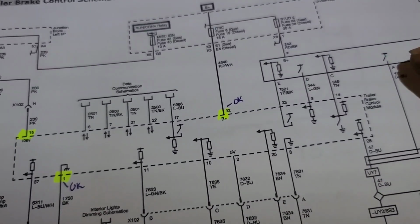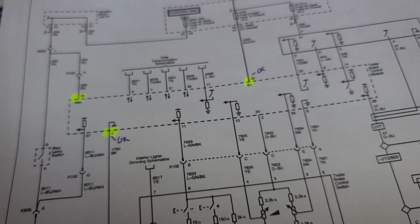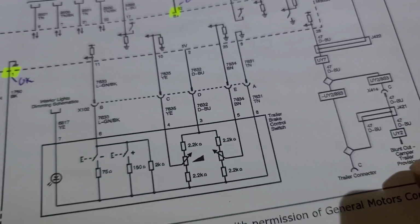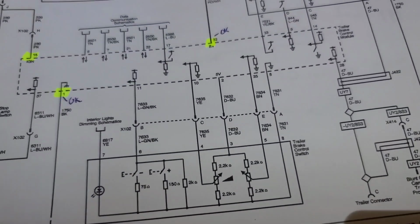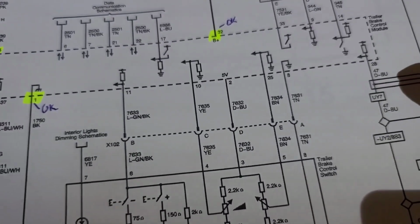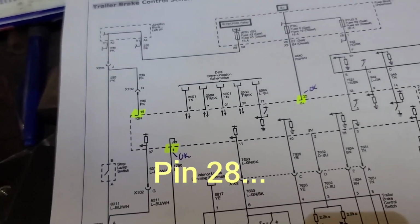So that looks like a feedback wire. And this goes out to the trailer connector, the blue wire, the dark blue wire. So I should have power on pin 29 now, because I've got that jumpered.